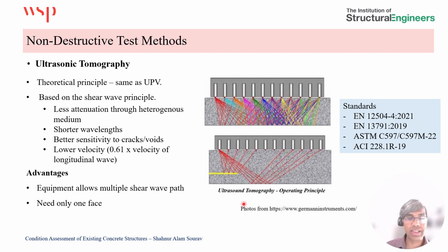Here you can see the signal transmitter and signal receiver. Once the signal is reflected at the surface of the defects or the void within the concrete, it will be reflected back, and based on that this equipment can produce a 3D internal geometry of that particular concrete element.